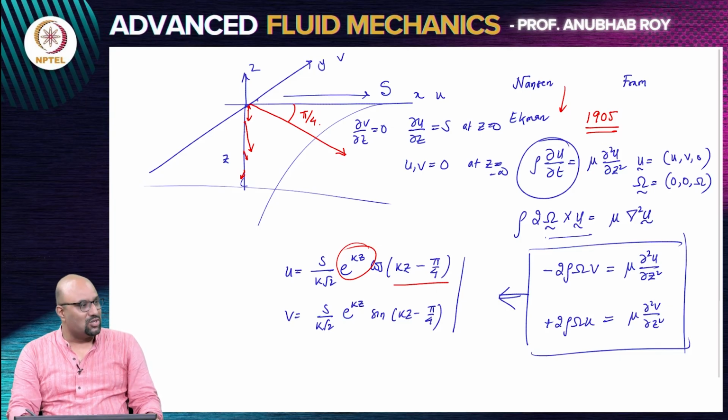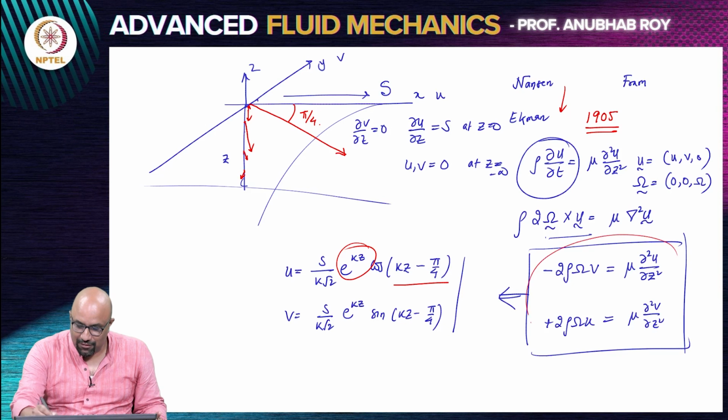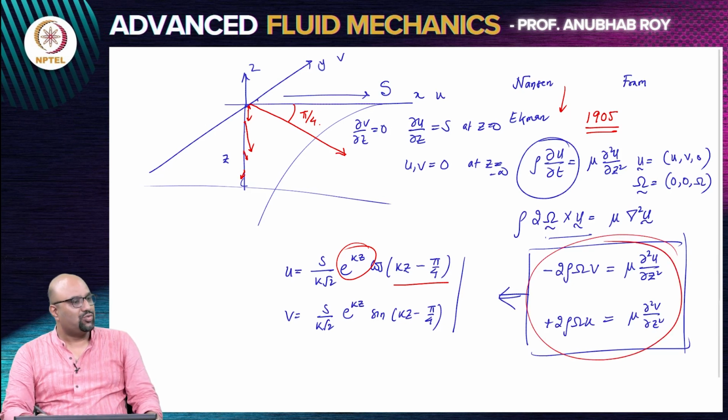But in fluid mechanics, you have obviously nothing less significant, definitely for us, which is Prandtl's contribution of boundary layer theory. And incidentally, in the context of geophysical flows and oceanography, you have viscous forces, howsoever small on the oceanic scale, being balanced not by inertial accelerations, but rather by Coriolis acceleration.